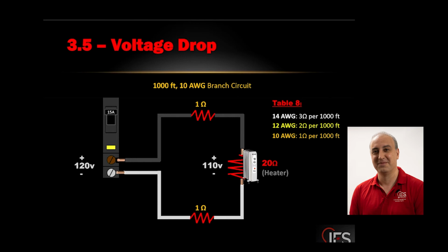But if you guys are mathematical, this is a simple ratio. You can do it in your head. So it's not complex, but I don't want to give you guys multiple ways to solve things. You know how to calculate voltage drop, the examples that you did already, right? So that's the formula. You put in the current draw, the distance of the wire, and so on, and you get the voltage drop. So that formula gives you what drops from 120. So if you did the calculations for this circuit, you'll get 110. You get 10. Yeah, this is additional, to teach you why it's happening, right?